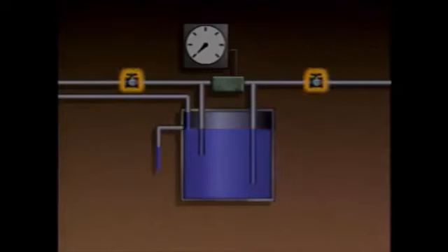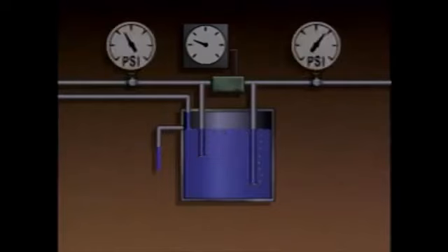During operation, regulators are used to adjust airflows through the two bubbler tubes until bubbles slowly rise from each tube. The air pressure needed to clear each tube of liquid is equal to the pressure exerted by the liquid above the bottom of that tube. Since the tubes extend to different depths, there's always a slight difference in the air pressure supplied to the tubes. So there's always a slight difference in pressure across the DP cell.